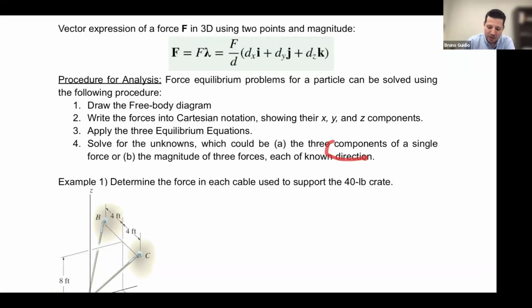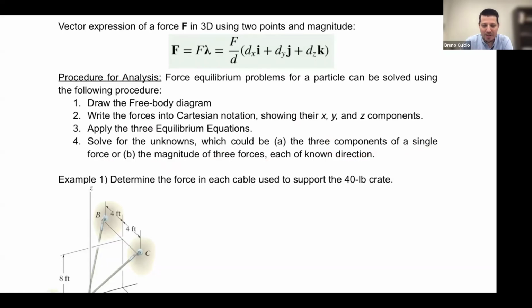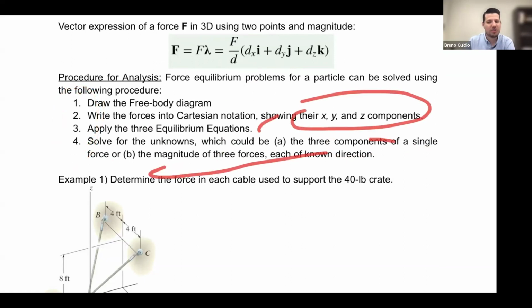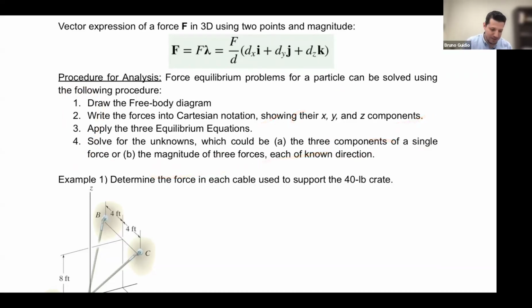The 3 components of a single force, the magnitude of 3 forces. What do we want to find? Depending on the problem, this is the step-by-step for solving those problems: free body diagram, XY components, equilibrium equations, and then solve. Okay, let's go for it.